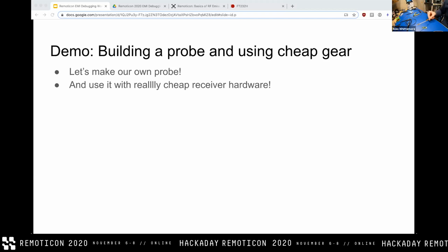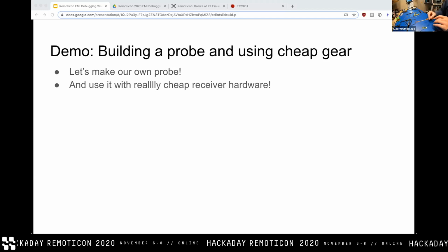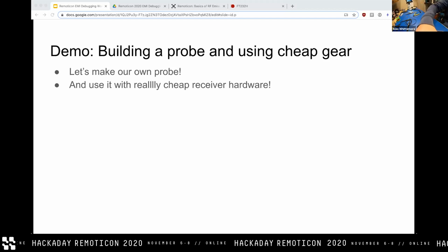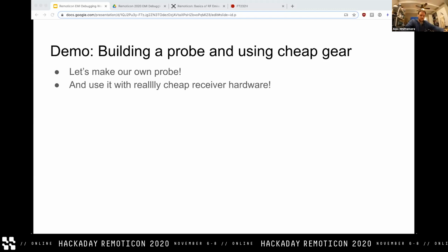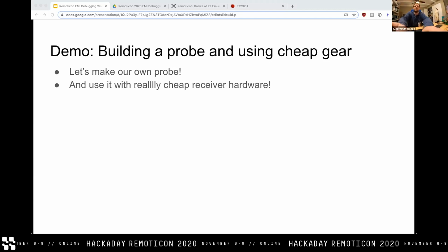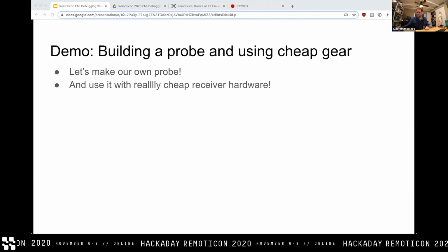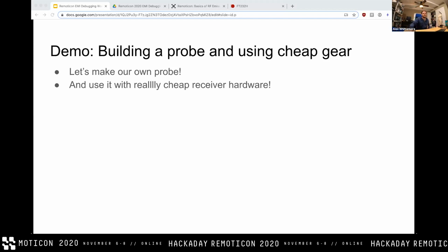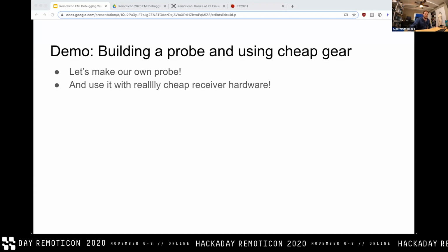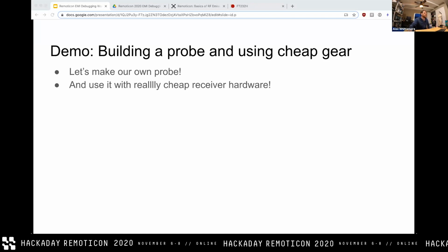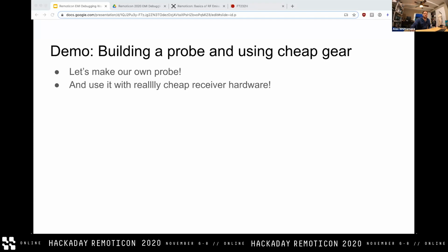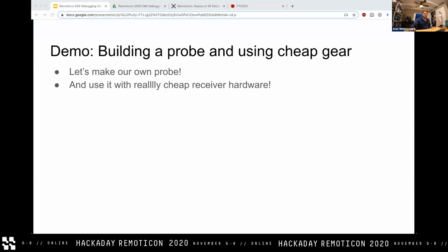Yeah, so obviously I didn't do the soldering. I'll try to go a little slow if anyone's trying to catch up, but that's really all there is to it to build a near field probe that is genuinely extremely useful for figuring out exactly what trace or signal or subsystem on your board is causing noise. Because it's not necessarily enough to simply wave your magic wand over.